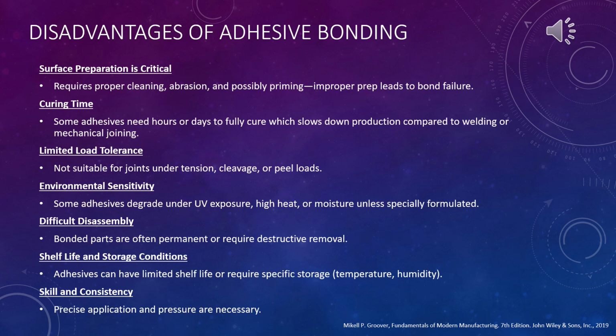Now the disadvantages of adhesive bonding. The first one is surface preparation. This requires proper cleaning, abrasion, and possibly priming. Improper prep can lead to bond failure, and what this basically means is any dust, oil, oxidation, or moisture can drastically weaken the adhesion. Some surfaces may need abrasion or priming, and this will add time and skill requirements to the process.